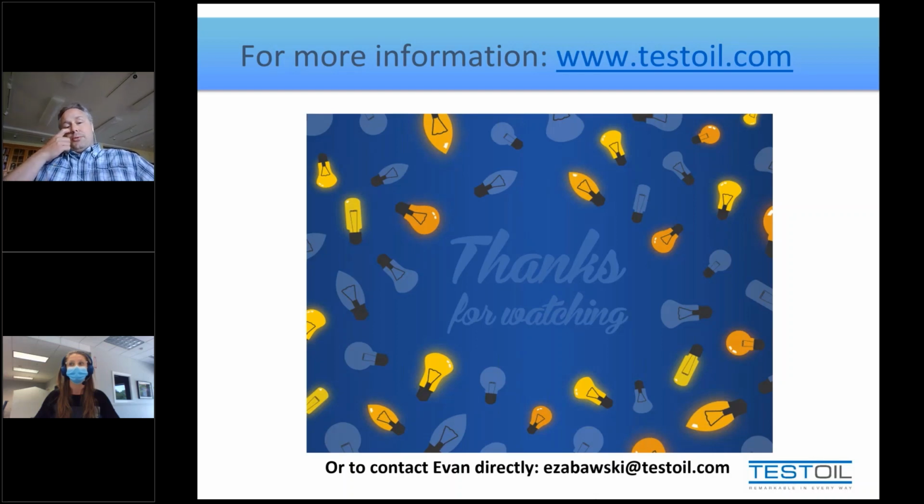Now, the reason I said there's two schools of thought, and the first was do nothing, is that's my school of thought. I'm not saying I'm right, it's just what I prefer. To degas a sample, to remove the refrigerant and see the oil without the refrigerant, may provide you with some data you think is better, but my logic is it's circulating as a lubricant with the refrigerant. So I like to see it unadulterated, with the refrigerants in it.